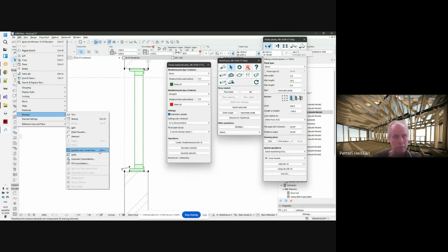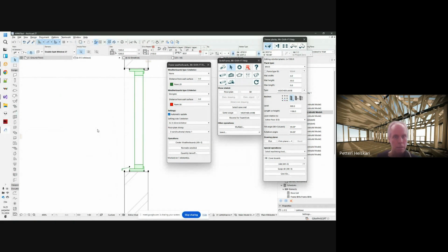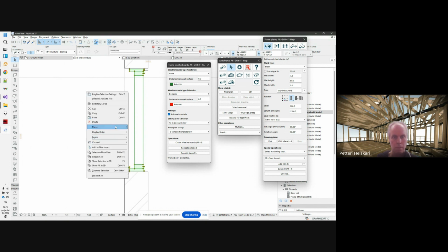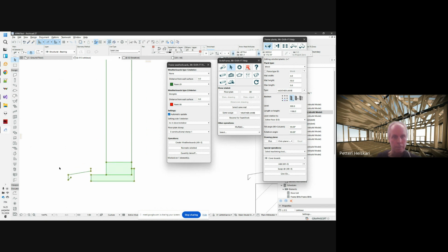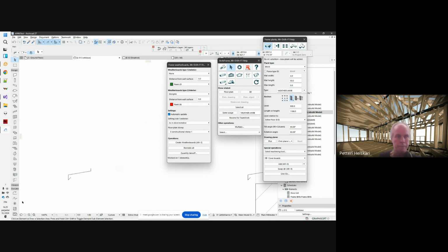So to get 2D version, or the end result, what we need is 2D fill. So to get that, I first explode these into separate lines. And to get those selected, this is the trick I've used. Maybe there is some other way. So undo and redo. Now we have only the exploded parts. Drag this slightly, and then the only thing we are interested in is this part here. Everything else we can delete.